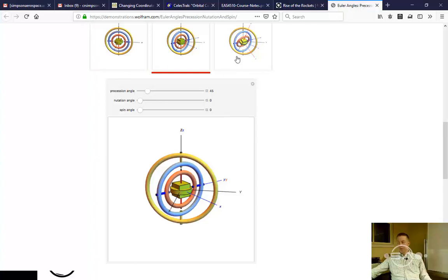So we've rotated 45 degrees, precessed, and then we have a nutation. All right, and so we rotate to get to that plane, or we nutate in order to get to that plane, and then we're going to rotate in that final orbit plane. So you notice now precession, that intermediate coordinate system is no longer the same as the nutation angle that we just used. And so that final frame, that body may spin in that frame, but we had to precess and nutate in order to get to that plane, and then finally we will spin in that plane.